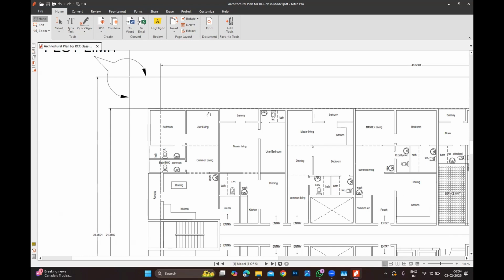Don't ever keep a bigger opening closer to the columns, closer to the shear walls. You understand actually? Some architects, on a lack of experience, what they used to do is keep the circulation opening, the bigger opening for the MEP shaft opening, closer to the column, closer to the walls, closer to the shear walls. Try to avoid this. I'm not telling it is mandated. Try to avoid this. If you don't avoid, what will happen? The wall becomes a cantilever because you don't have any kind of stiffness around it. It demands huge reinforcement. I understand.